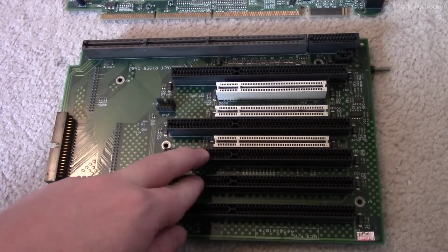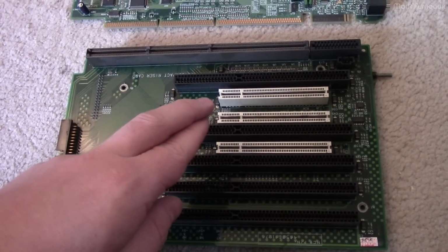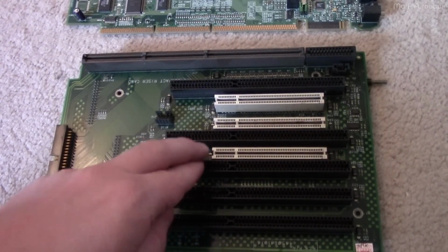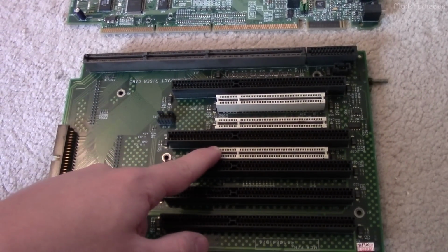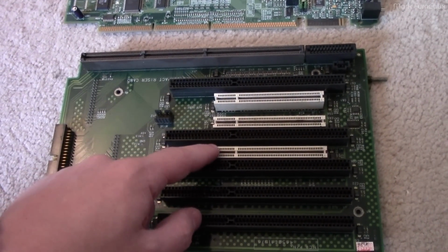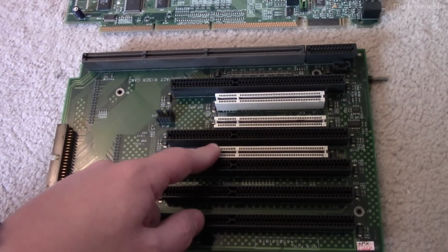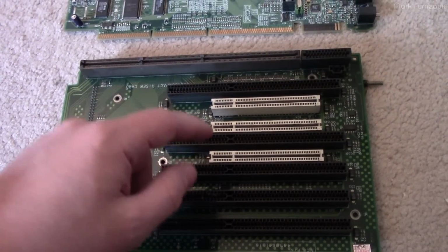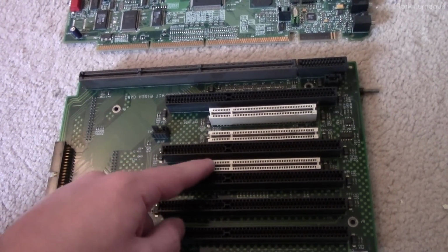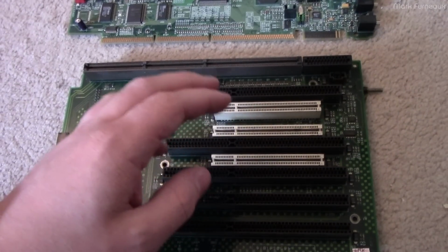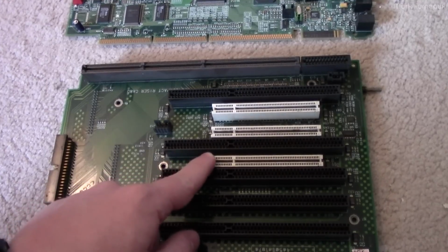So it means that you can run those bridges in reverse, and you can actually connect a PCI Express device to a PCI bus through essentially the same bridge chip. And the only way this is possible, because of course PCI was designed before PCI Express and so has no knowledge of PCI Express, is that they designed things into PCI Express to allow it to be backwards compatible. So essentially, for something to be fully PCI Express compliant, it must support operating through one of these bridges.